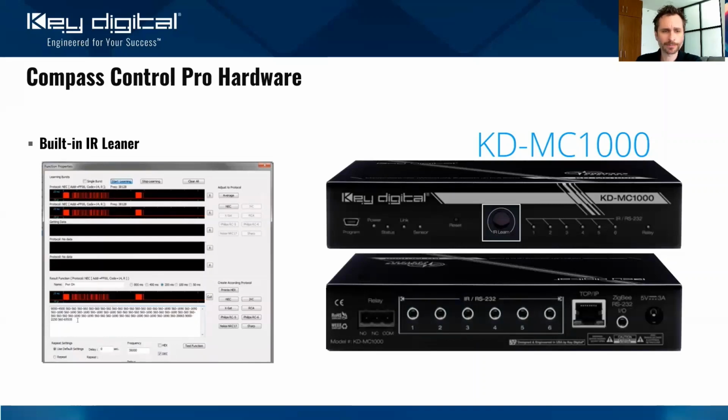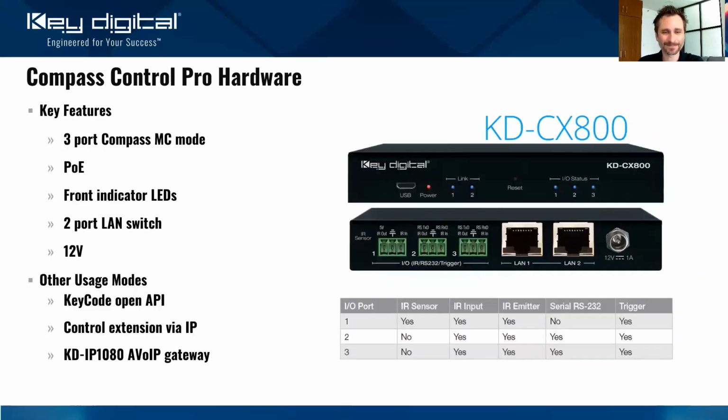I wanted to show you real quick with the built-in IR learner what that capture looks like. It's very nice when you are in the IR database manager and you begin learning your IR codes. You even see this visualization of the IR burst, which is really excellent for making sure that things look uniform and you're working with a capture that looks reliable, right?